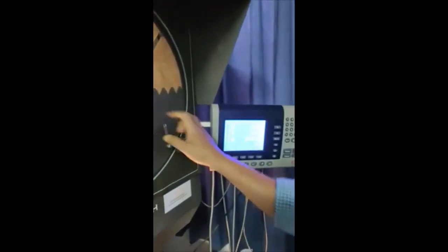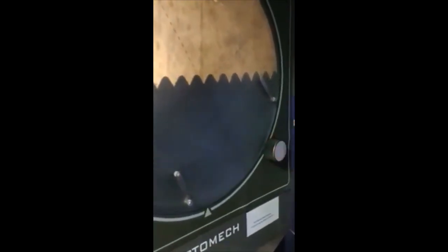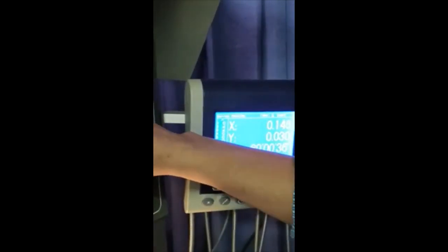Now let us come to angle measurement. This is a rotary knob. You can rotate this axis to measure the angle. Suppose I am rotating this thread here now. You make it zero. Now adjust the subsequent surface of this profile angle, 69 degrees. Like this, the angle of the gap and the angle of the thread can also be measured. This thread measurement is now completed.